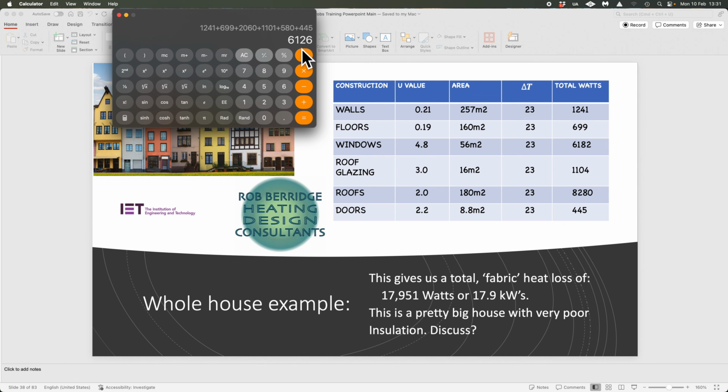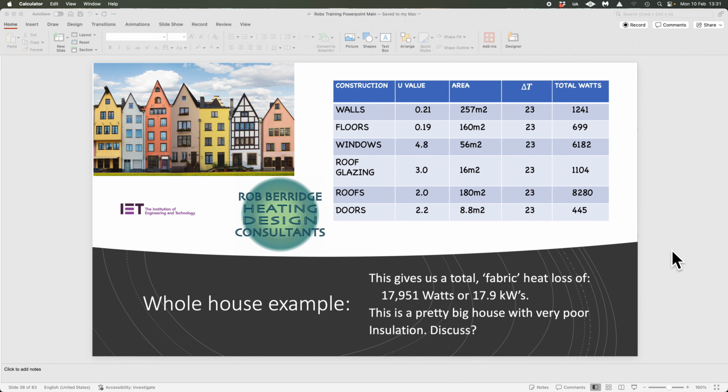Now that is pretty epic, and I think anybody can see that just by doing some longhand heat loss calculations on a building fabric. Now, is that building now heat pump ready? Well, yes, of course it is. And that's going to be perfect. That's going to run at a wonderful, wonderful low temperature system for these guys. So that is what I class as doing due diligence on a building when you're doing a survey, to make sure that that survey is absolutely correct. So there you go. This is why I think it's very important to do these first of all, and pass on to your clients. Plus, it gives you credibility as a bona fide and a competent installer.